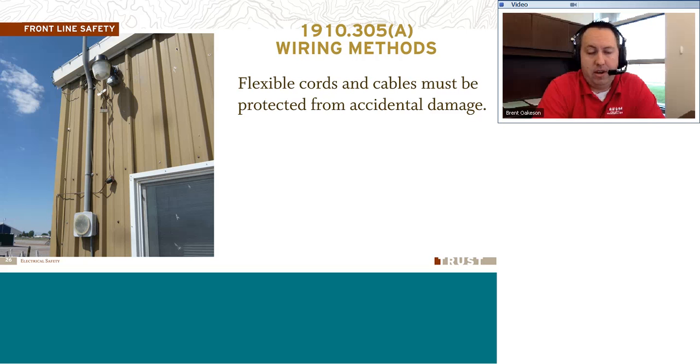Here we have an example of a couple of extension cords and a three-way outlet where they're plugging in and extending things, but these aren't the right type for the exterior. Think about the weather and the rain and things that could get into there and cause damage to that equipment and the wiring there. So watch your temporary wiring. Make sure that they're used for the right locations, right type, and right sizes.